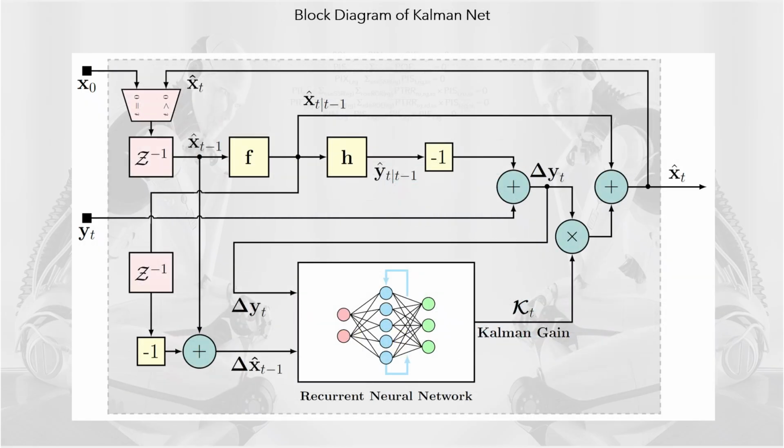The figure shows the block diagram of KalmanNet. KalmanNet is based on a hybrid and interpretable data architecture for real-time state estimation in nonlinear dynamic systems, with partial knowledge of the stochastic domain. The covariance matrices Q and R are not available. These missing statistical moments are only used to calculate the Kalman gain matrix, Kg. KalmanNet combines KF with a recurrent neural network, RNN, to address model mismatches and nonlinearities. KalmanNet learns Kg from data and combines it with the global KF flow.